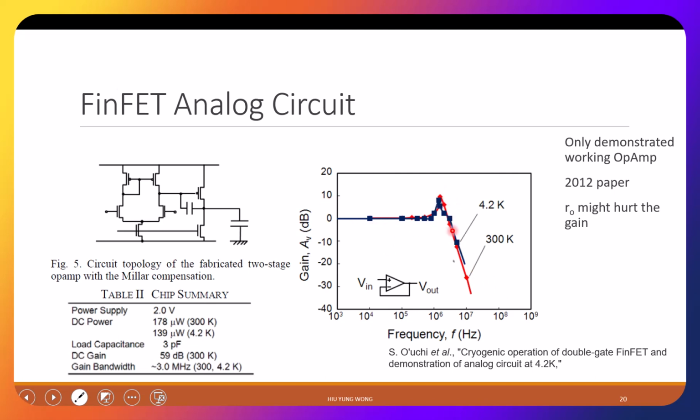The point is just to show you that they perform well. You do not expect this one to have a higher gain because it should act as a unity gain buffer. By the way, 0 dB means gain equal to 1. To convert something into dB, you take 20 log of the gain. But we will discuss more later when we talk about L10A.